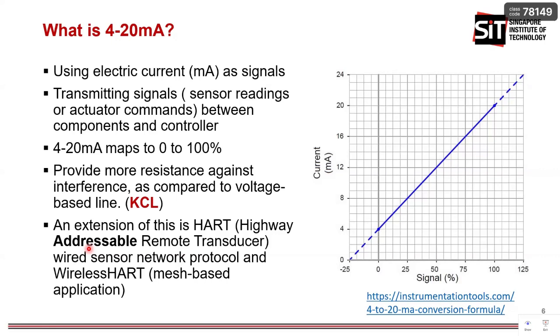All right, in the lab, for the next few days, when you come back to school for your lab sessions, you will see how a Modbus device can be addressed. How can you call that particular device using its unique ID so that you can extract information from it. And why is addressable useful?